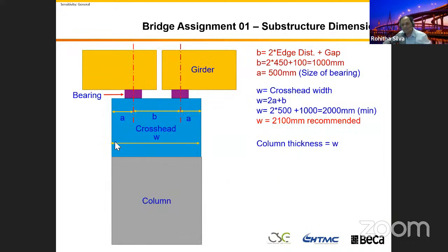Even in terms of the design performance, it's not good, especially for earthquake design and detailing. You don't want a kink in here. Even in terms of the force transfer mechanism, because they are heavily loaded structures, it's very hard to design this thing. Not easy to design. So the width of the column and the width of the crossbeam is the same.